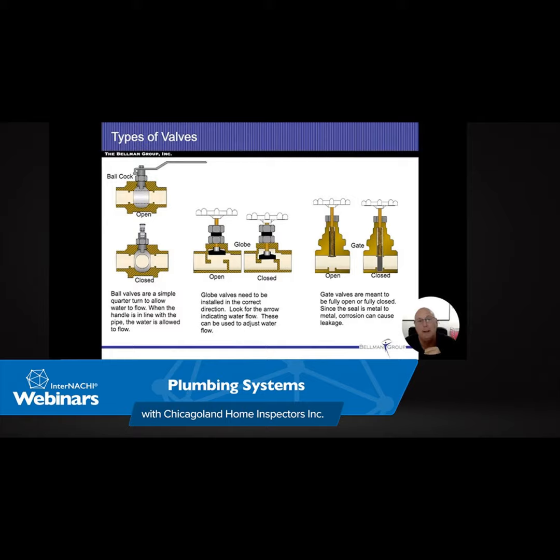I would like you to know the difference between hard temper and soft temper. Most plumbing that we see with copper pipes is either going to be type M or type L. Most underground stuff that you're going to see is going to end up being type K. That's the thickest, and it can hold up to the most amount of stress. Inside supply lines for copper, everything is pretty much hard temper.